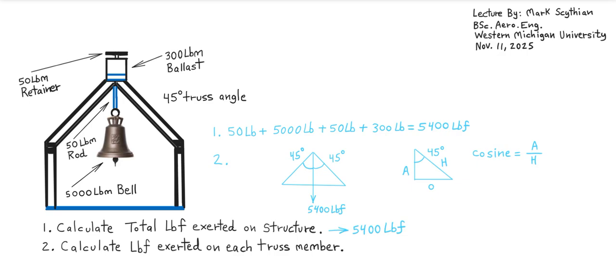And so since we're dealing with the opposite, adjacent and hypotenuse angles, with the opposite being irrelevant across the vertical load downward, the adjacent and the unknown truss force hypotenuse, we can just solve for cosine, or adjacent over hypotenuse.